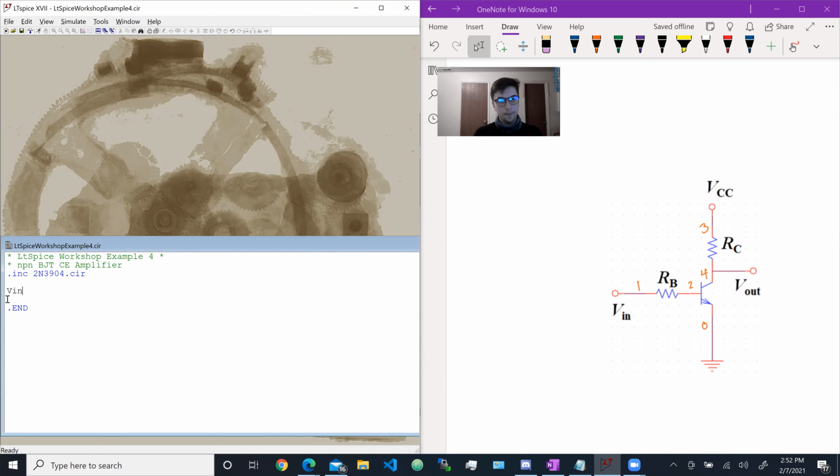So VN, I'm going to do from 1, 0. Positive is going to be the 1, which we already have there. I want to do a DC sweep, so I'm going to do DC. I don't have the example that I made. Oh yeah, I do actually. It's right DC 0. I'm going to say 0 volt. Or wait, no, that's not how you do it. 1, 0, and then I'm going to say 0 volts to start with. We're going to do RB. It's going to go from 1 to 2. And I'm going to do like 51K.